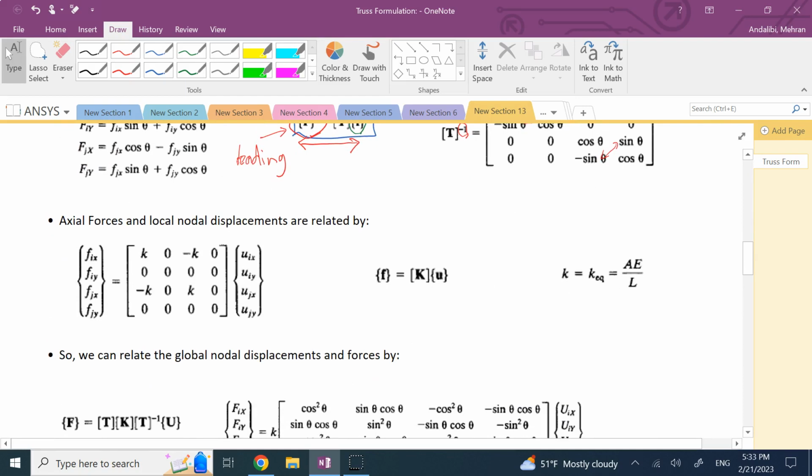Well, we know that since the members are two-force members, the members are under pure tension or pure what? Compression, that we have seen in the past, right? And if a member is under pure tension or pure compression, then we know that the total elongation in the member is going to be what? We know it. It is F times L divided by A times E.